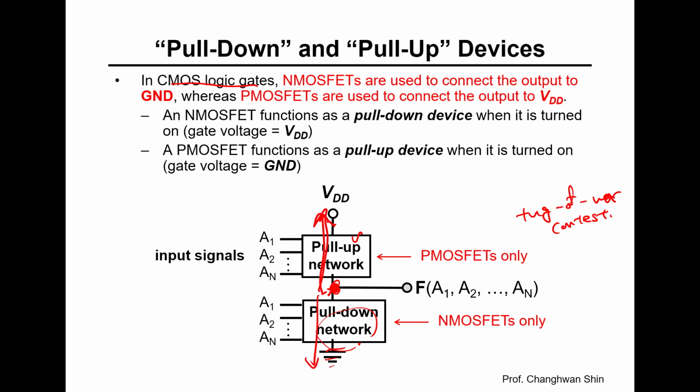For a given logic function, we construct complementary networks of these devices. The pull-up network consists exclusively of p-channel MOSFETs, while the pull-down network uses only n-channel MOSFETs. Input signals control both networks in a complementary fashion, ensuring that when one network conducts, the other network is inactive. This is like a well-coordinated dance where partners never step on each other's toes.